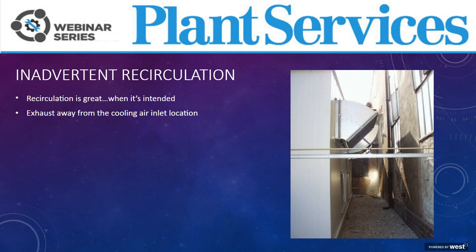We've established that compressed air equipment generally draws cooling air from its immediate surroundings. This can be a problem if some equipment exhausts toward the inlet of others, which we saw before. This is referred to as unplanned recirculation, and it's where the cooling airflow for one machine is accidentally ingested by another. So again, this picture just shows that the inlet is directly near the discharge ducting, and so what you end up having is a cooling loop that you don't really want to have, so your warm air is going back into your inlet.